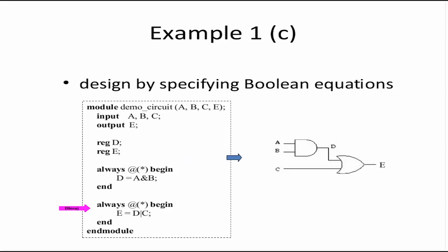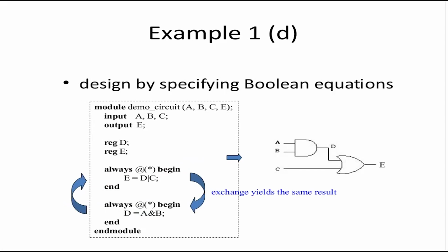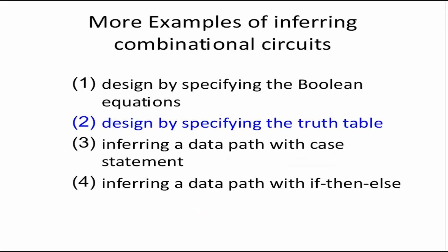So in Verilog, statements within one always block will go sequentially, but all the always blocks are parallel to each other. Even if we exchange the code, we write one always block below the other, we switch the order, it doesn't change the synthesis or simulation.